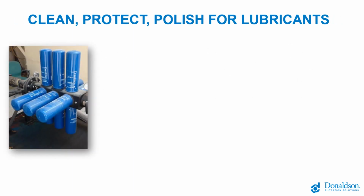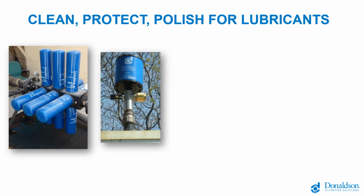Just to give a refresher on what the whole philosophy of clean, protect, polish looks like for lubricants. You're doing a high level of filtration on a fairly thick fluid at the point you take possession of it, so you're offloading it through 4 to 10 or 12 filters maybe. This is a 12 filter manifold. As it goes into your storage tank, you're protecting it there with a breather and possibly purging air over that headspace to prevent condensation and water buildup in the system.